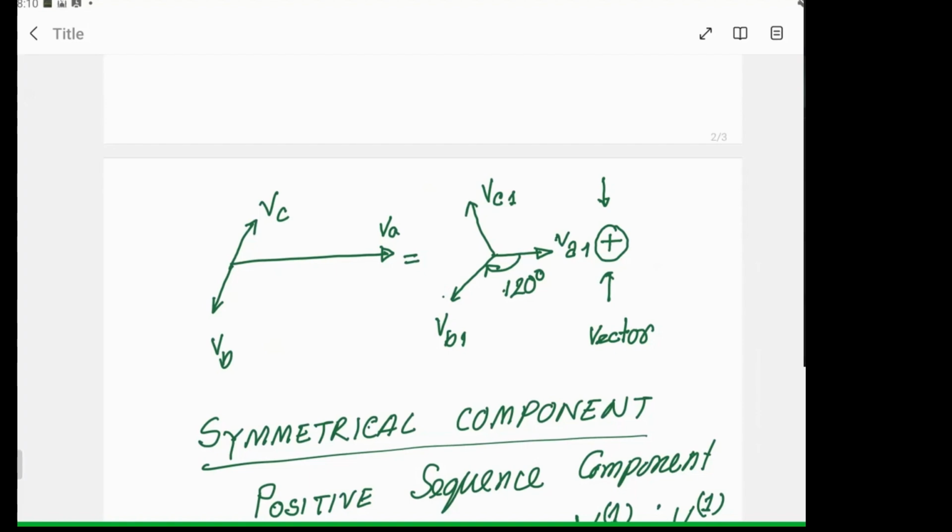If you change the frequency, two signals of different frequency are not the same signal even if magnitude and phase are the same. But in power systems, we are lucky: we are using the same frequency, so we are not considering frequency. We only have to consider the magnitude and the angle, which belongs to the phase. That means whenever you have a quantity with two characteristics involved, you cannot add them with normal addition. You have to do a vector addition or phasor addition.